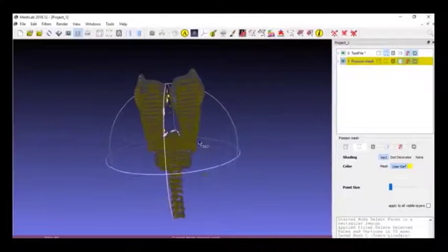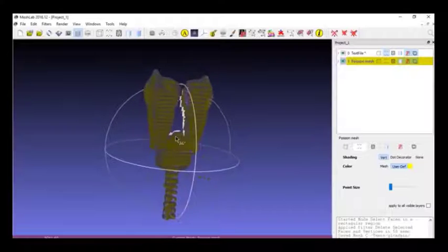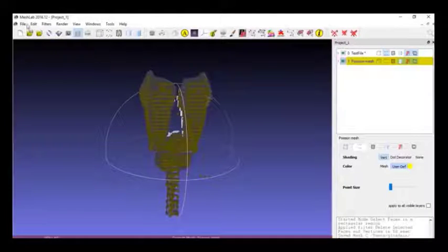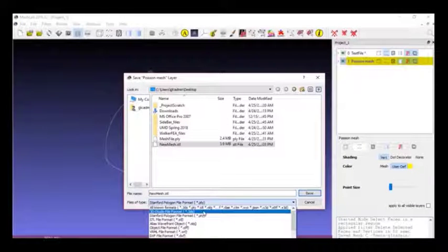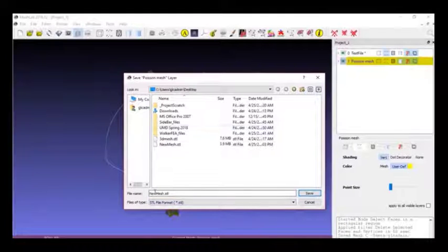All right, so we cleaned up our mesh file here, got the space in between the two parking meters cleared. And so we can take this now that we have a 3D mesh, and import it into Creo. So the first thing you have to do is export the mesh, changing it to an STL file format. So that is right here. And then we'll save it as a new mesh. So I've already saved it here.